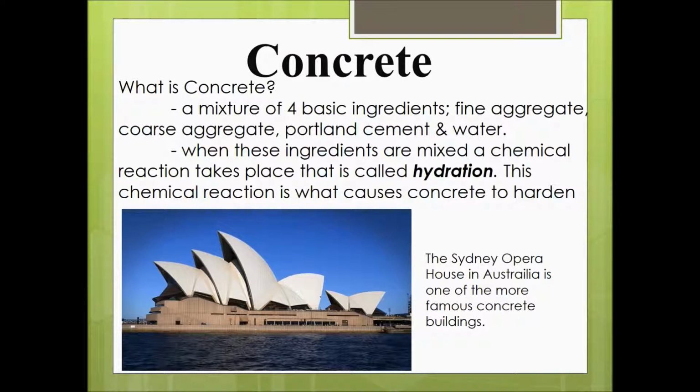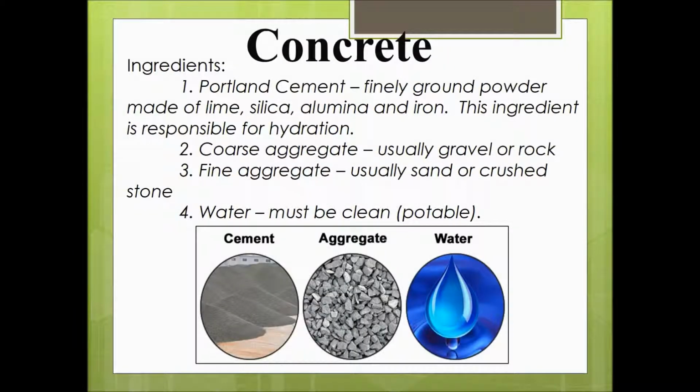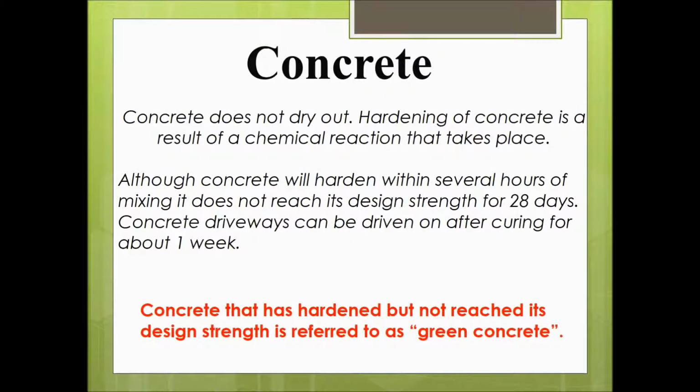There's a lot of things you can do with it. So here's the ingredients. You got, like I said before, Portland cement, coarse aggregate, fine aggregate, and water. For those 28 days, it's called green because it has not reached what's called the design strength.